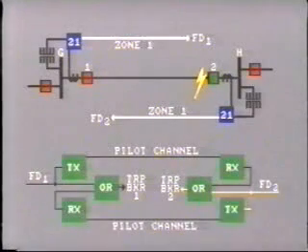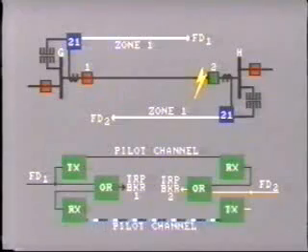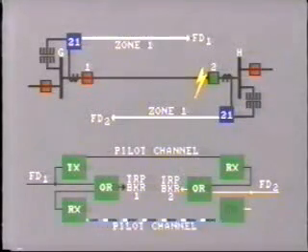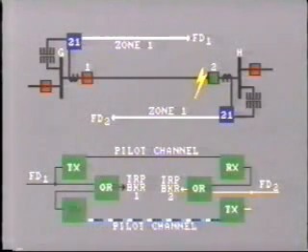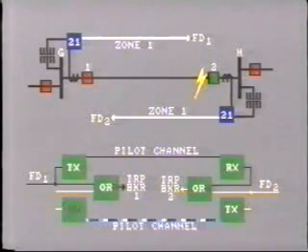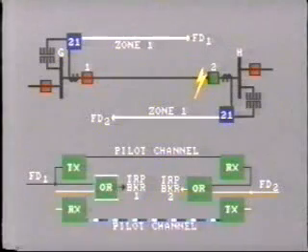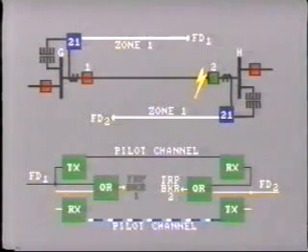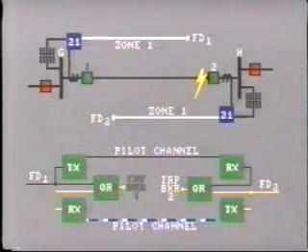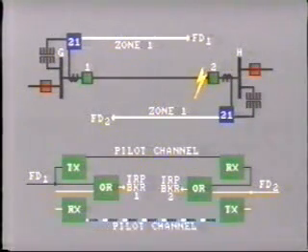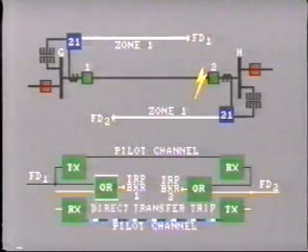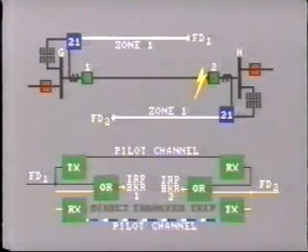time, FD2 switches the transmitter from guard to trip. This immediately starts transmitting across the communication channel, where it's received by the receiver at station G. The receiver sends the signal to the OR box, where it passes through to energize the trip circuit of breaker number 1. Note that it does not need a signal from fault detector 1. It is a direct transfer trip.